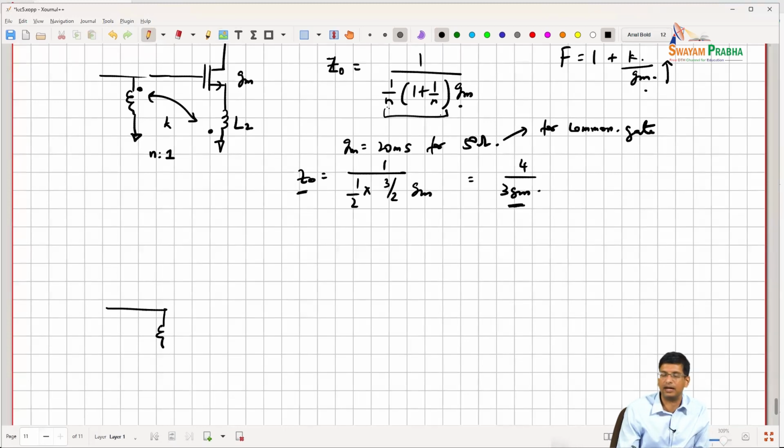There's been also follow-on work where, remember the source current and drain current are related, so instead of doing this kind of transformer feedback across the source current and degenerating, I can do the transformer feedback from the drain. If I do it across the drain, then I'm quite sensitive because there is gain from input to output.